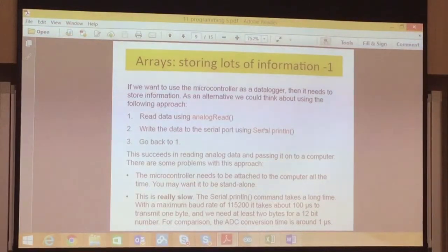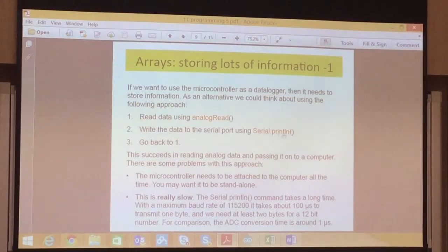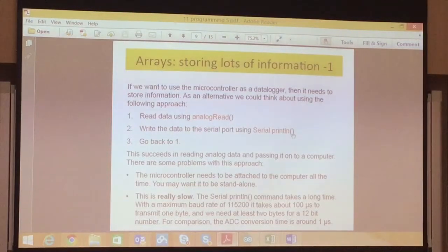Now the issue comes: how fast is this Serial.println? If you want to do this kind of very fast capturing of data, you have to consider all these factors. The analogRead is actually very fast because your microcontroller is very fast. But how fast is your Serial.println? That's the other question. The Serial.println depends on the bit rate you specify.